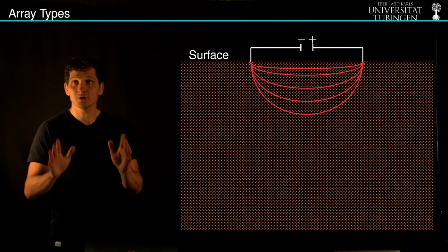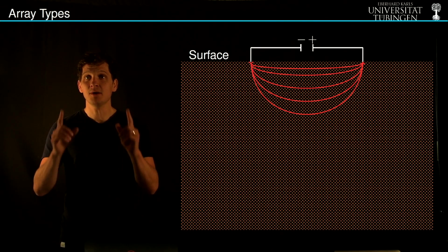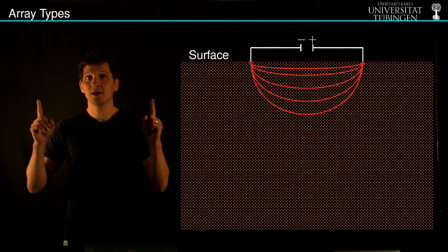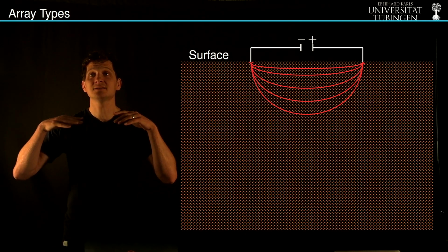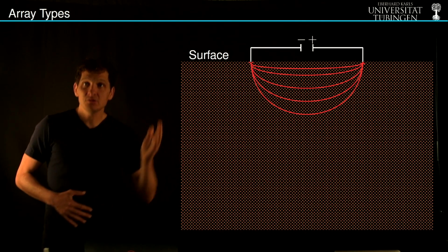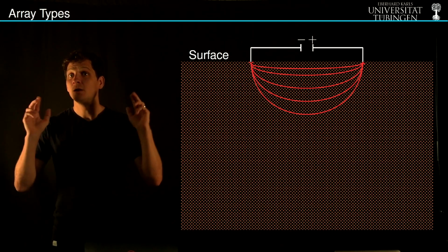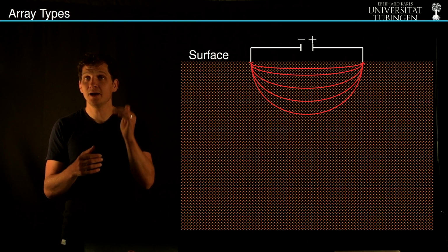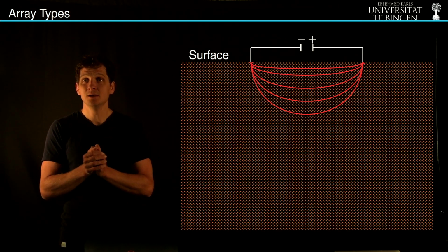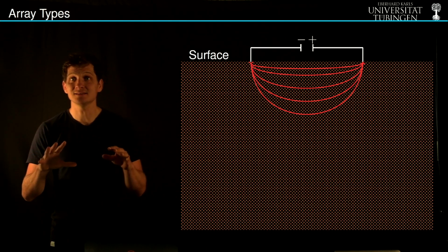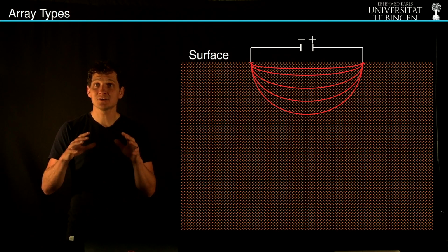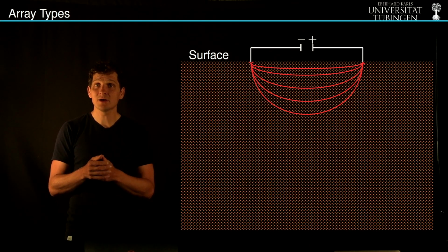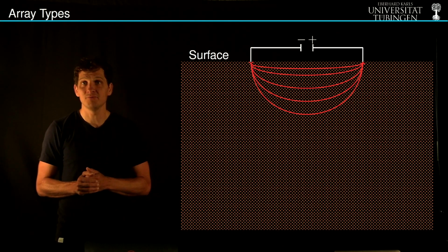So as a first order metric, you should definitely keep in mind that if the current electrodes are spaced far apart, then you get a deep penetration, but a correspondingly weak signal. If they are close together, you have a much shallower penetration. And in the exercises, we will quantify this concept a little bit more rigorously using the theory from video 1.